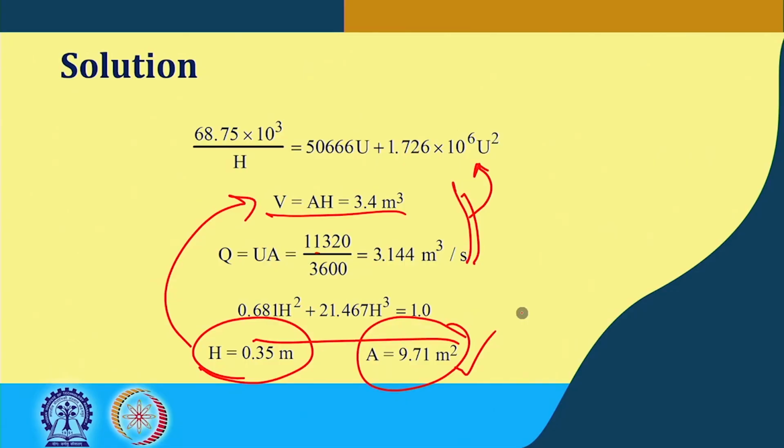So we find that critical point, and till that critical point we find a relation based on either the first part of the Ergun equation, which is linear, or the part varying with the square of the superficial velocity. In the next class we will again be solving another problem related to this, and we will cover some other basic theories to complete this section.